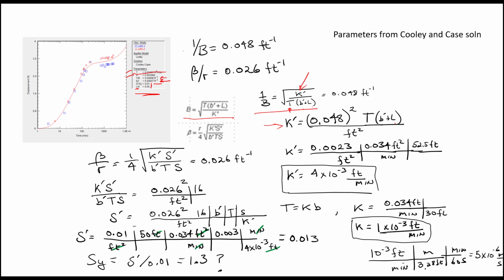And if I fill in the values here, then go through and multiply that out and check the units, those cancel, and I'm going to get feet per minute. And I do that out, and I get that for the hydraulic conductivity of the saprolite. So that's pretty nice. The other tests that we did, the other analysis, they weren't really giving us information about the saprolite, and this one does. This gives us this hydraulic conductivity value.